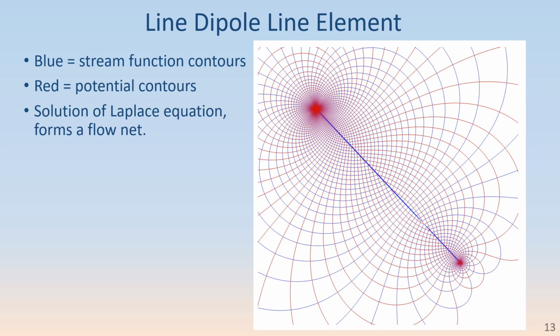That turns out to be just right for a fracture or drain element. And the strength of one of these elements is the jump in the stream function, which equals the discharge that's being conducted within the drain. And that can vary along the line irregularly depending on the value for parameters per line. There are singularities at the tips, which are point sinks in this case, as opposed to vortices.